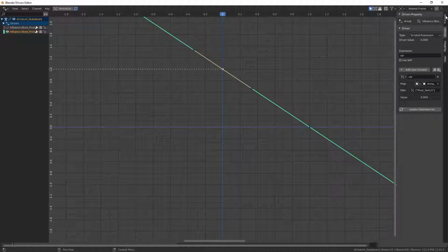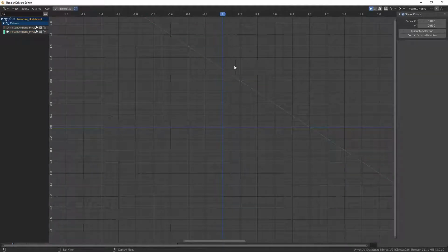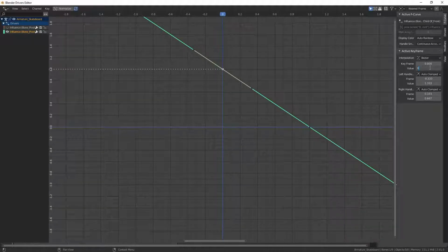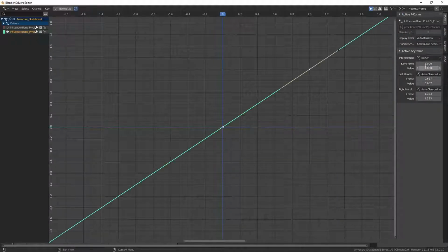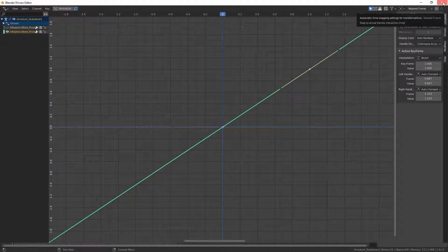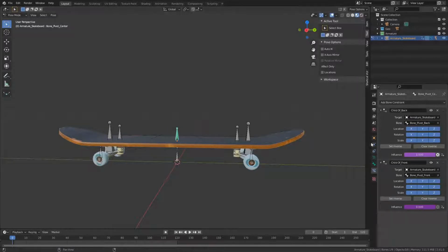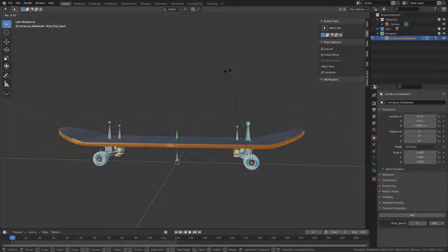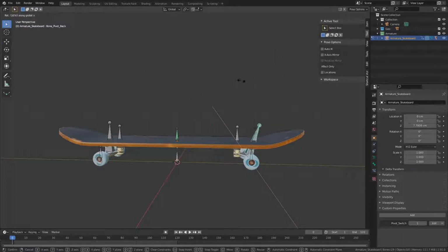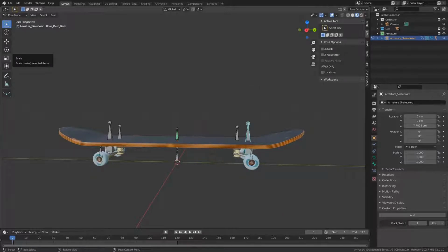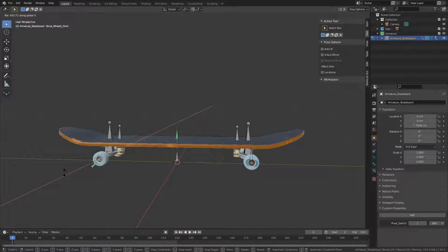and again in the F curve we want to reverse the direction, so 1 should be 0 and 0 should be 1. Close that. Now we can see that the influence is different. Let's test it out. Back pivot has the control, front pivot has no control. And if we change the pivot switch to 1, the front pivot has the control and the back pivot has no control.